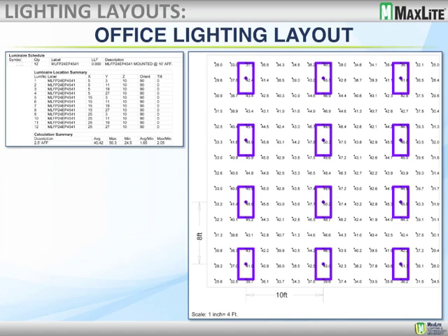LEDs depreciate after 70,000 hours, so that's a long length of time. So we're just putting anywhere from 0.9 to 0.95, depending upon the application itself and what the client is asking for. We have had some LED light loss factors requested at 0.7 at times. And so those are very conservative estimates then. Very, very conservative, and we question why they want to do that, and they say it is a very dirty application. So it's understandable.